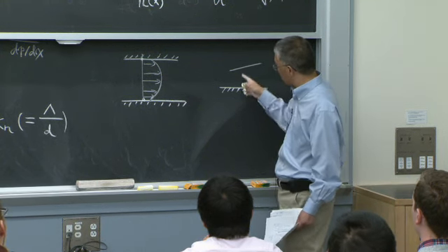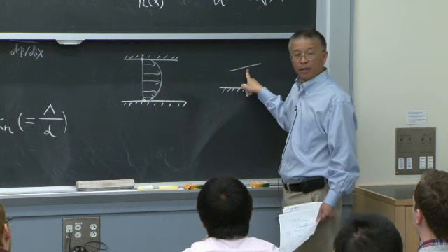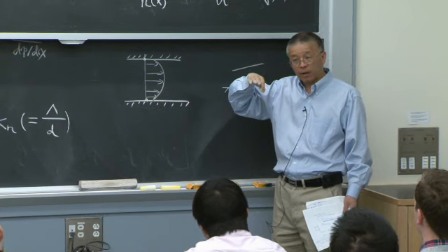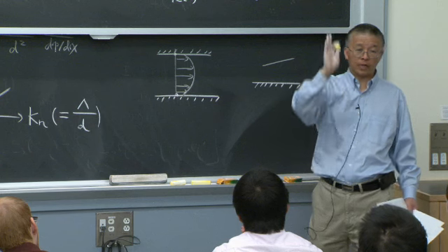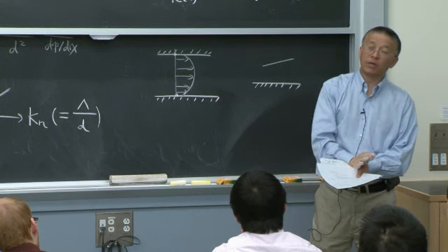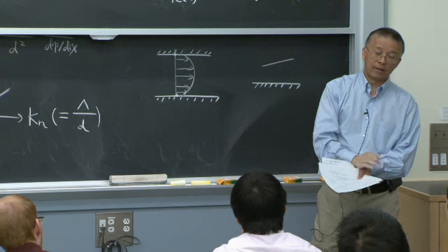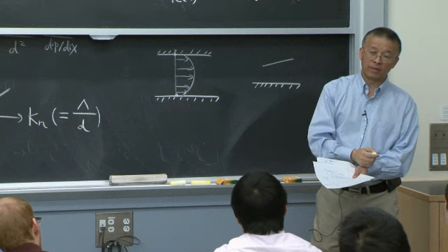And for the Reynolds equation, the rotating disk has a magnetic head. And this magnetic head has an inclination, right? So it's like an airplane. You have an angle, so that gives you lift. And that lift is very important because otherwise your head will crash into the disk, right? And this disk is rotating at about 10,000 RPM, very fast.